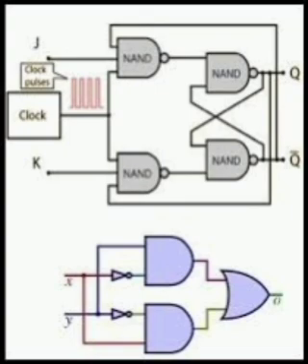Whereas SR flip-flop from other flip-flops: S equal to D and R equal to D bar. JK flip-flop: J equal to D and K equal to D bar. D flip-flop: D equal to JQn bar plus K bar Qn. T flip-flop: T equal to JQn bar plus KQn. SR flip-flop: S equal to TQn bar and R equal to TQn. JK flip-flop: J equal to K equal to T.